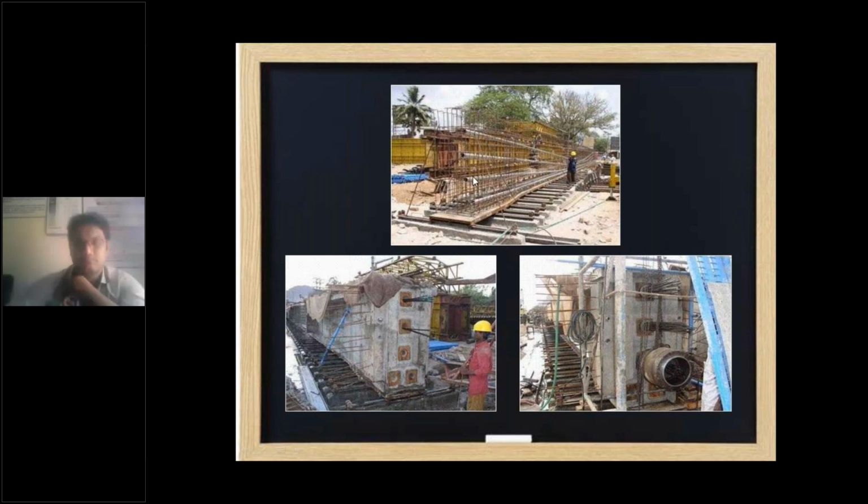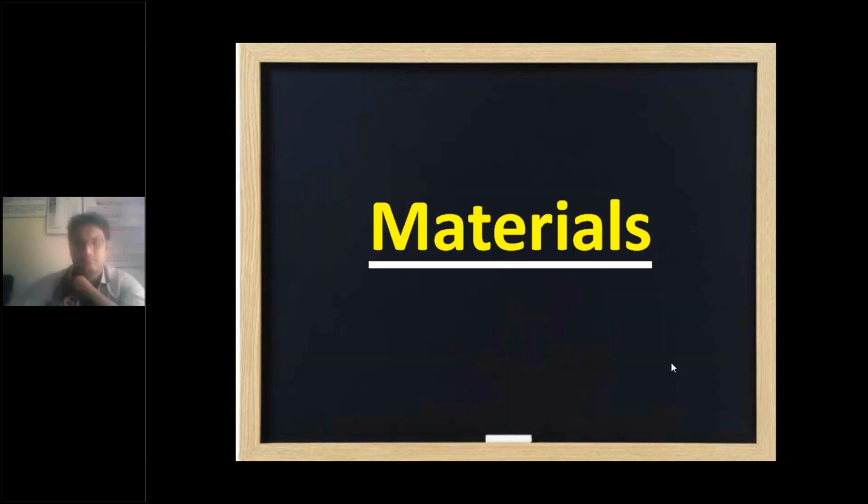I will try to show you one model, which was developed by me, where you can see how the post tensioning can be applied, and how the member is going to be hogged in the upward direction. This is the first stage of post tensioning, where sheathing is provided inside. After that, it is cast with concrete on the casting bed, and finally after attaining its 28 days strength, it is stressed with the hydraulic system, right? So these are the stages.